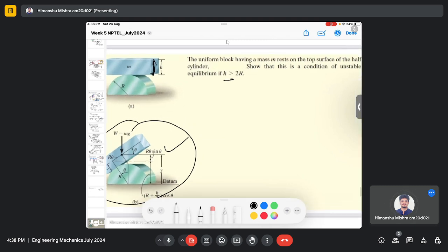As you can identify, there is no elastic member, there is only a gravitational force. So when we use the energy principle, we need to be concerned only about the potential energy due to gravity, because the potential energy due to the elastic member is 0, since we assume that the blocks are rigid, not elastic in nature.